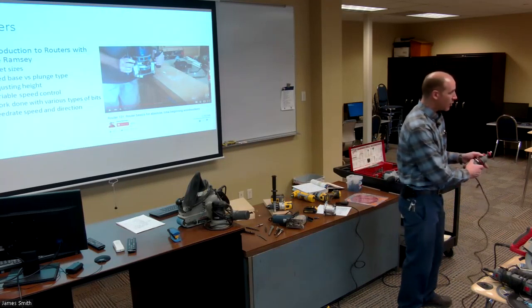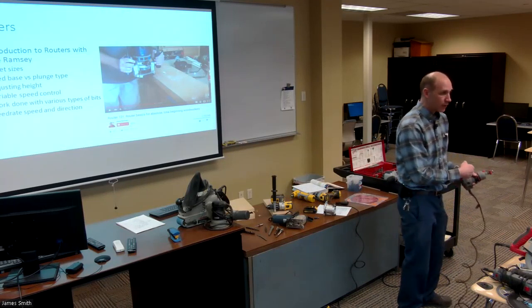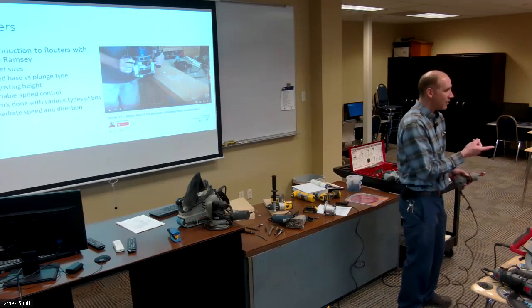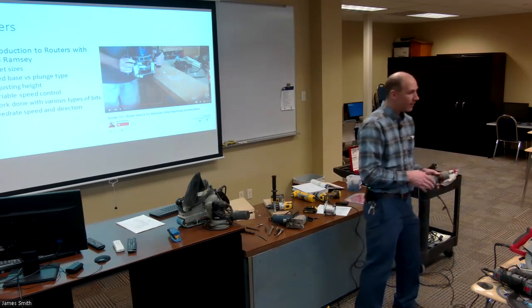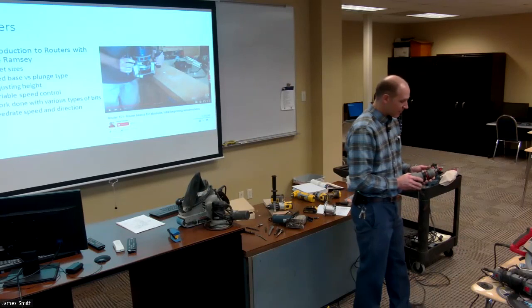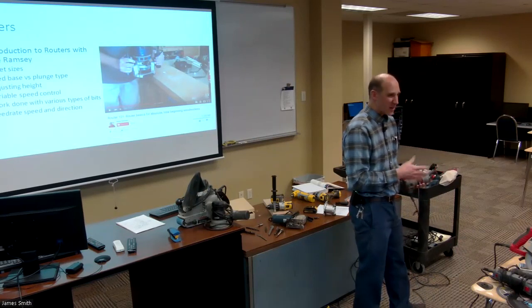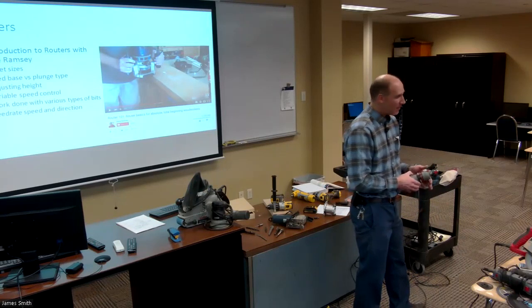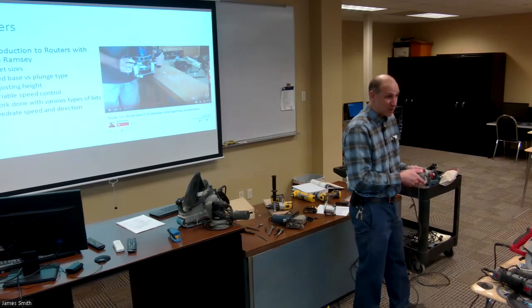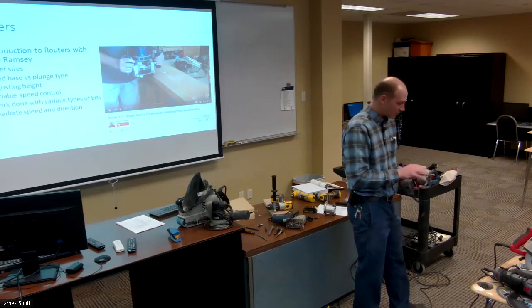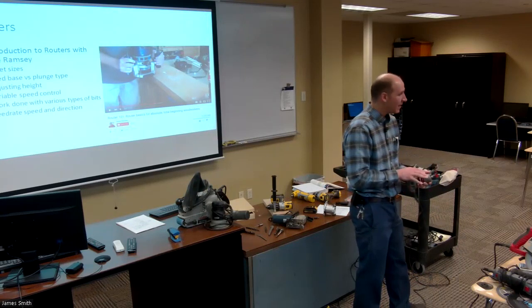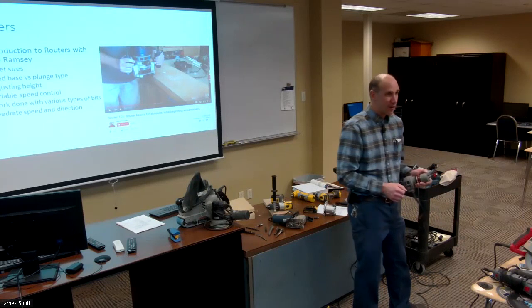Just don't ever push that button when you turn on the router. You'd think that would be kind of like duh, but some of these rotary tools, especially Dremel tools, they put those buttons in the most convenient places, and when you're just trying to hold it, you accidentally push on those buttons. And if you didn't realize what that was for, it's very easy to make that mistake. And now you have no way of locking your shaft to take that collet off.